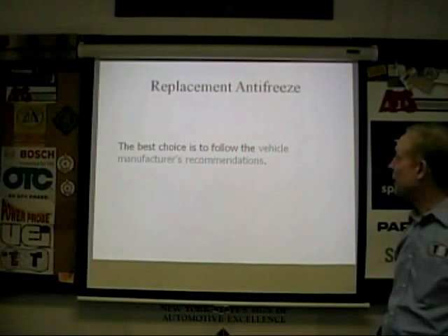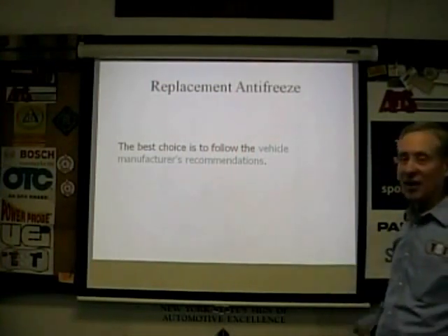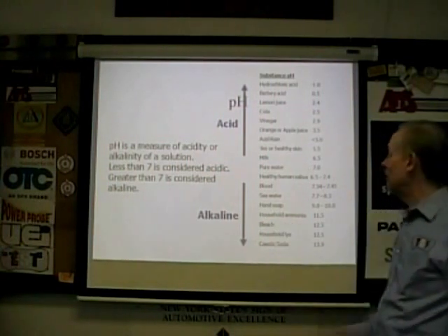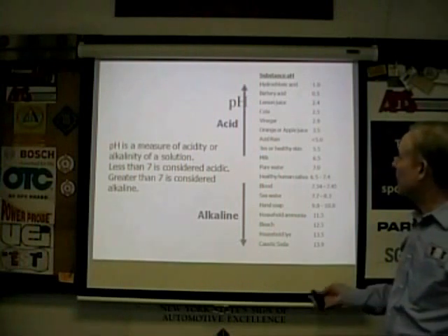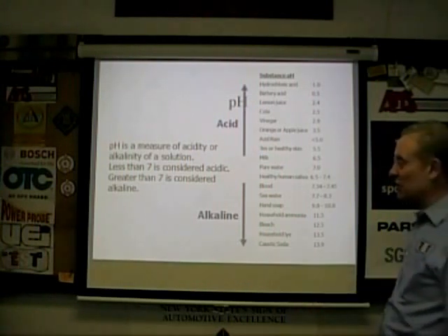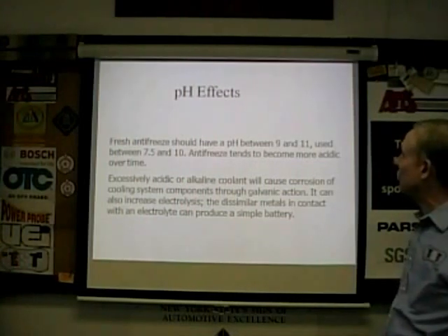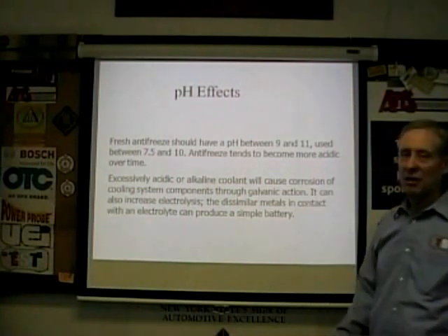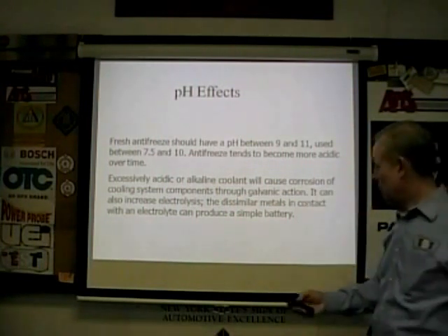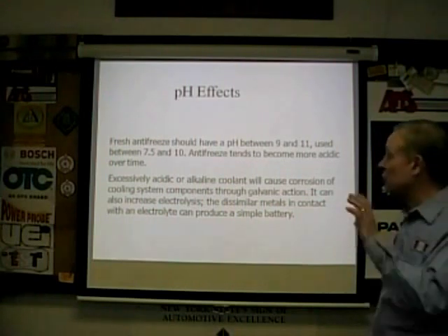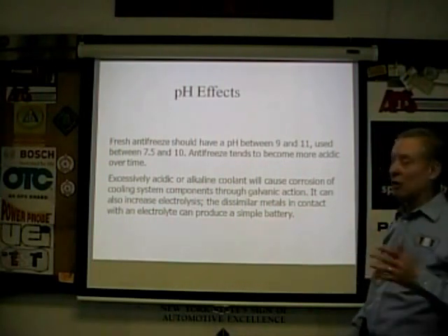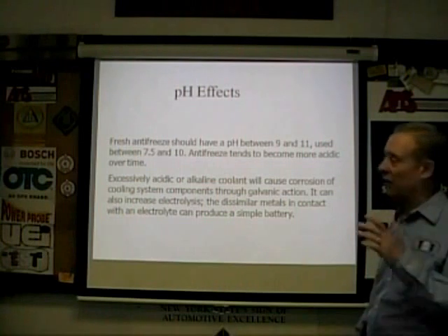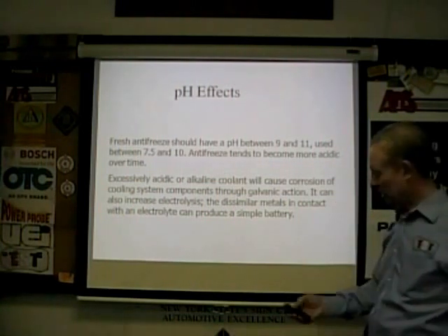All right, replacement antifreeze. What I've been saying. Use the manufacturer's spec. There's the thing on pH. You don't have to memorize it. You could have this there, in your shop to look at. But in reality, all you have to know is that different pHs react with each other, different chemistries react with each other. All right. And a fresh antifreeze should have a pH between 9 and 11. This spec has changed over the years. Again, there are test strips. You can test this stuff. As a rule, as soon as it's anywhere away from the original spec, in my opinion, I get rid of it. I don't wait until the thing fails gigantically. That's just trouble waiting to happen.